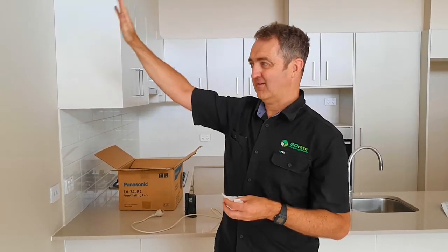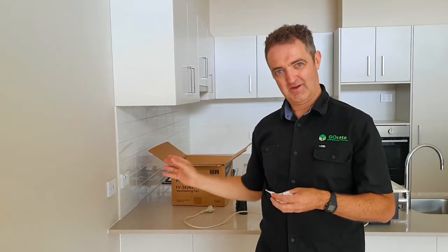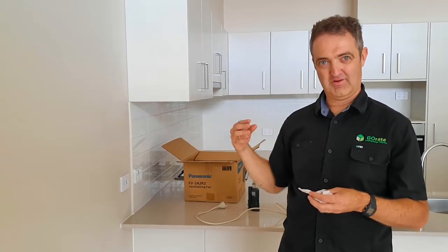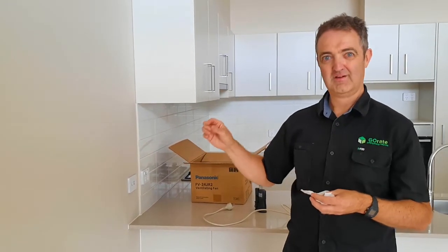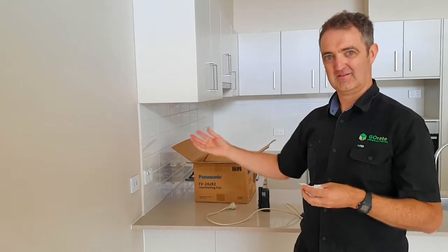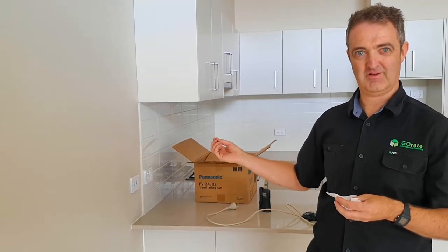So what that means as well, just like before we had the air from the roof connected through the exhaust fan, in this wall we've got air connected through the wall, through the power point and inside the house. And again, that's air we're breathing, and it's also uncontrolled air. So as far as keeping air from coming in from outside, it's just a really bad situation where it comes through and you're breathing air that you don't want to be breathing.